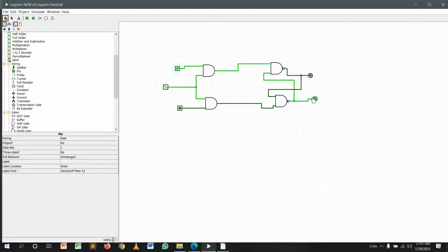Another output is 0. So this output is 0 and this one is 1. Then I set those two inputs to 0, and when I input the clock, it will not change anymore. Therefore it's a memory location. And when those two inputs are 0 and I input clock pulse as 1, it's also a memory location. Therefore it does not change.